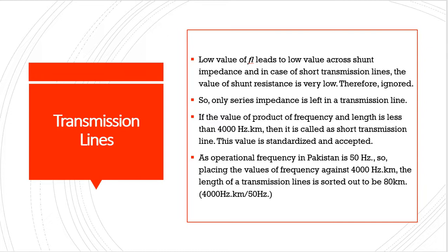So, if we ignore this value of capacitance across a short transmission line, then we can also say that this value can be suppressed or neglected, and only the series impedance is left inside the transmission line, right.